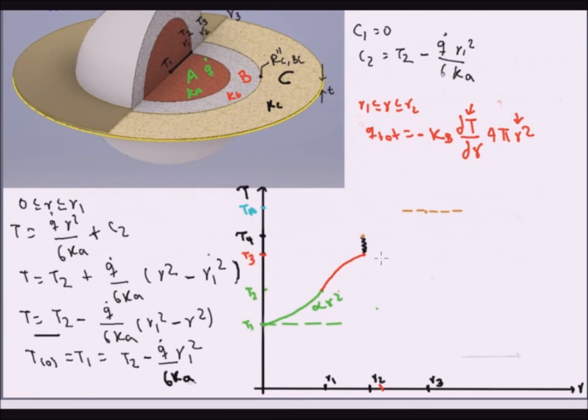But here the temperature profile behaves similarly to the sphere. Your heat rate, or your temperature gradient, will be the highest when you're closer to the center, because as you get farther, more surface area will be exposed, and the temperature of that surface area will be a lot more similar to the surrounding fluid than closer to the center.